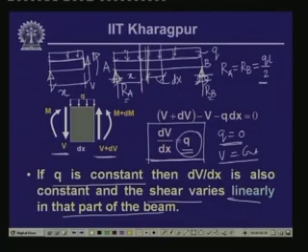So, since we are talking about shear force V, if we take the vertical equilibrium, V plus R_A minus q times x equals 0. This gives us that V equals qx minus R_A, that is, qx minus qL/2.